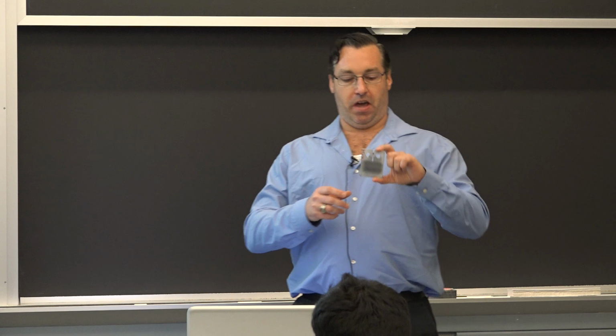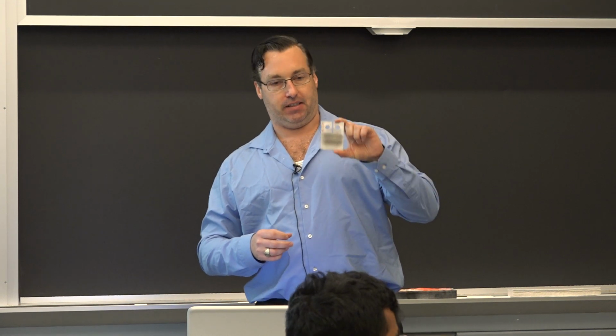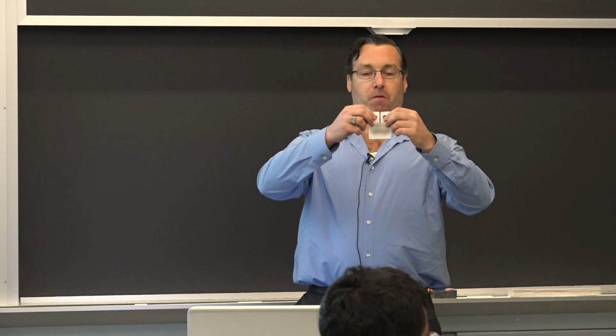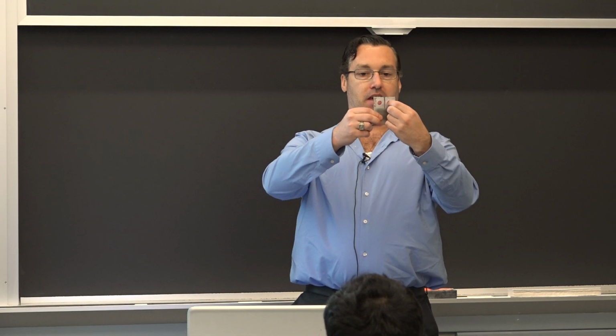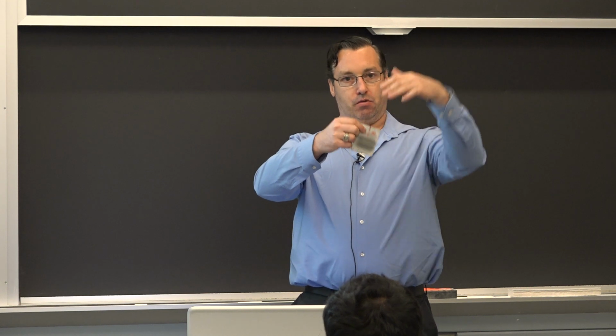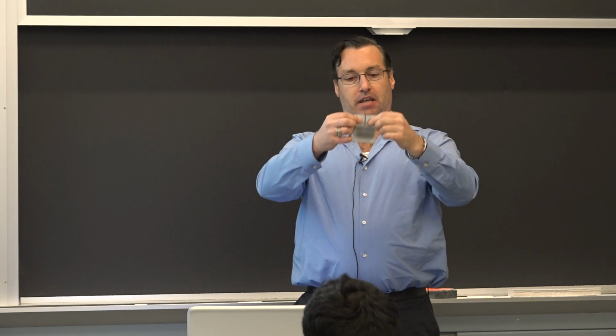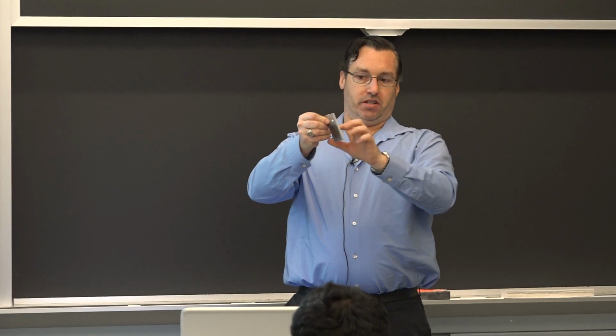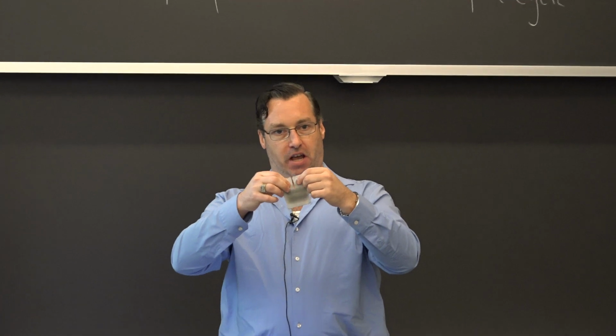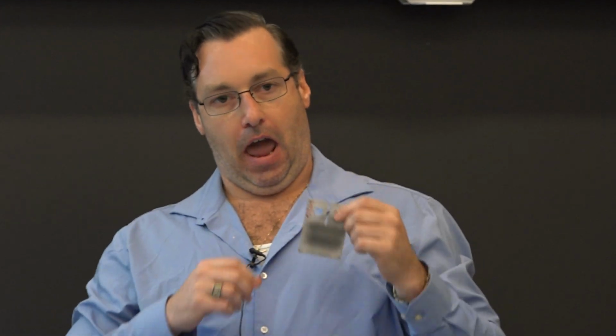So what we have here is what's called a CT, compact tension specimen, and this is for fatigue testing where you will do cyclic loading. And what happens is the component goes into a universal testing machine, it gets gripped on either side here, and it actually forces this crack notch over cycles to see when that crack initiates, and then at a certain point after the crack initiates, the propagation rate, so it's called fatigue crack propagation rates.